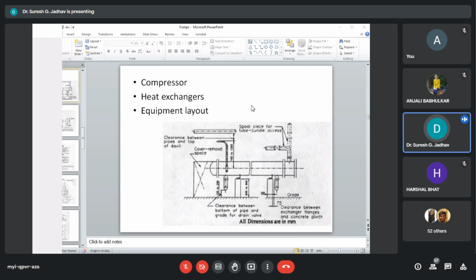The piping shall be arranged in such a way that no temporary support will be required for removing the channel and tube bundles, and provide easily removable spool pieces, flanged elbows, break flanges, or short pipe runs to provide adequate clearance for the operation of tube removal. The pipelines with valves and control valves should run along the access way, close to the exchangers.